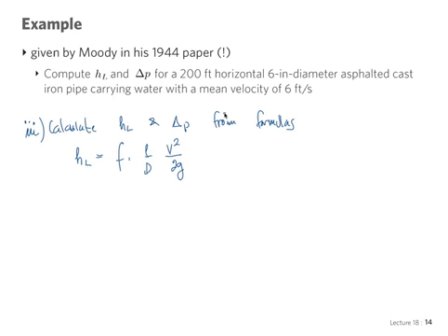Did I get that right? I think so. Yeah. So here I don't have the extra row, do I? No, remember that we said for turbulent flow we can write it the same way. The only difference is that the friction factor now is not 64 over Reynolds, it's some unknown function which we obtained from the Moody chart. But we have it now, 0.02, and we have L over D, 200 divided by 0.5.